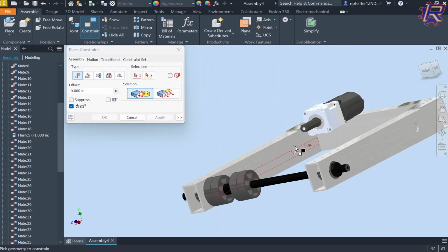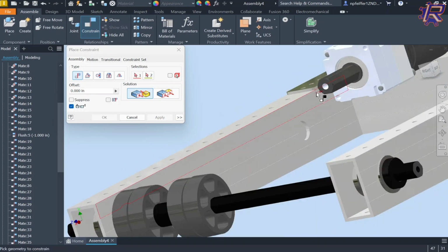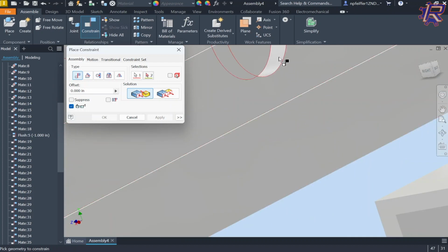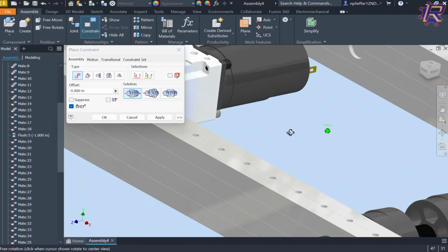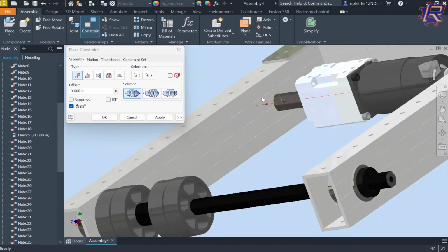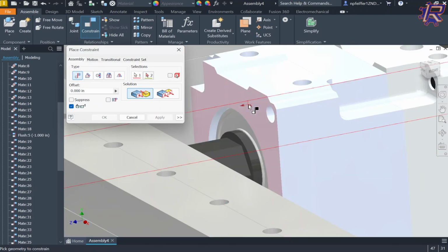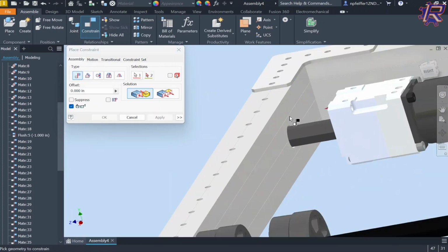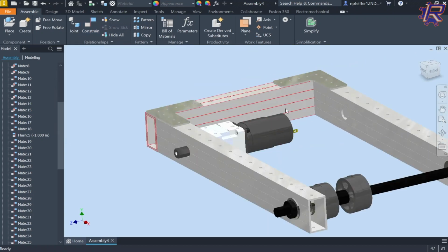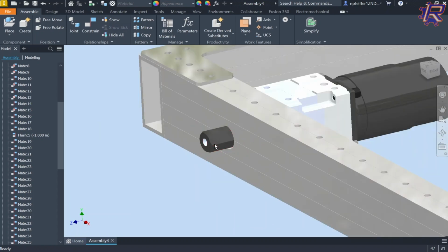And as I said before, we're not going to be using a bearing here because, frankly, in CAD it's not that necessary for stuff like motors. So I'm just going to constrain this circular axis right here to this circular axis. And yeah, just like that. Now I'm going to bring this all the way so it touches the face. And now you can imagine that when this motor receives power, this part of the axle will spin.